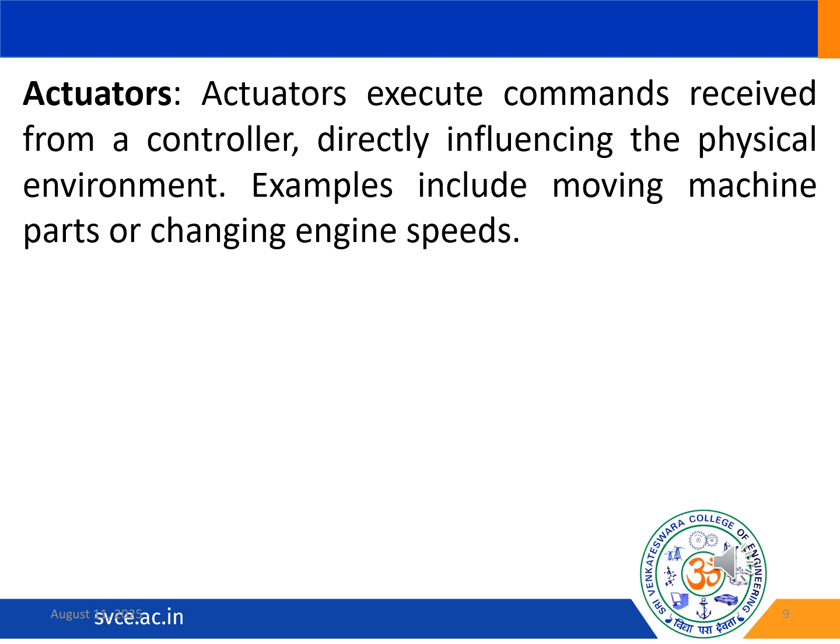Controllers regularly receive measurements from sensors as input. The measurements are stored, processed, and continually fed into a control function, mapping all these measurements to an output value, for example using a differential equation. The output value is then sent as a command to one or more actuators.